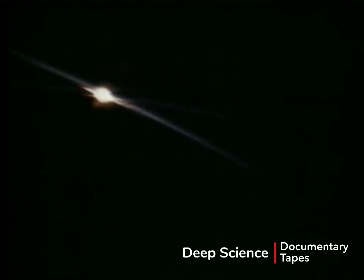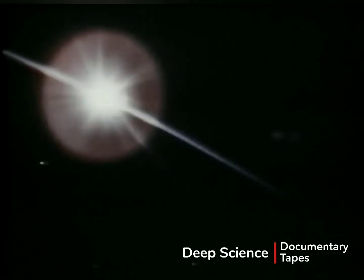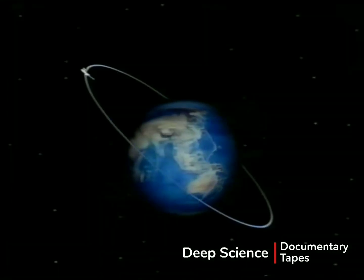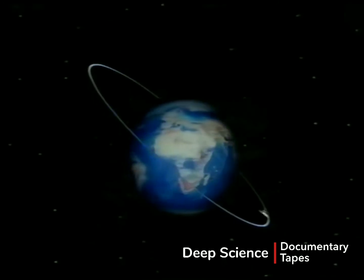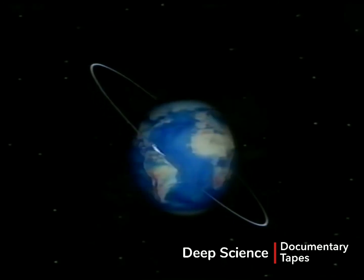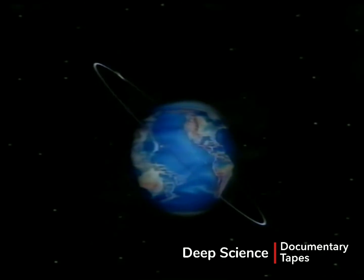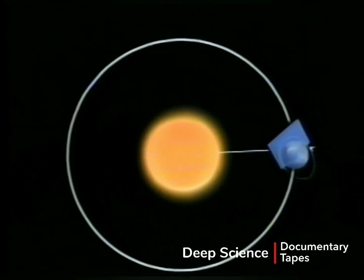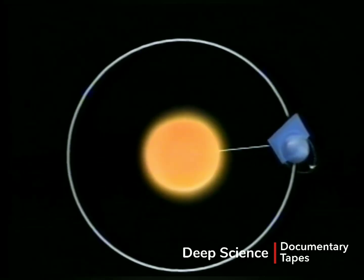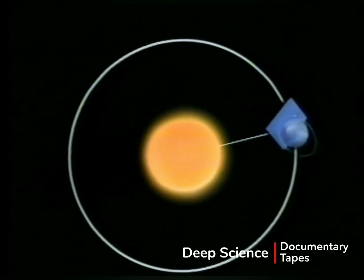These take advantage of the precession of the orbital plane caused by the Earth not being a perfect sphere. All sun-synchronous orbits are highly inclined retrograde orbits which precess eastward around the Earth's polar axis at the rate of 1 revolution per year. Since the Earth-Sun line also revolves eastward at the rate of 1 revolution per year, the orbital plane will maintain a constant orientation relative to the Earth-Sun line.